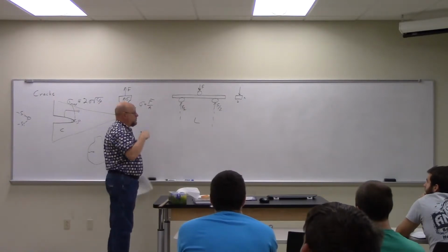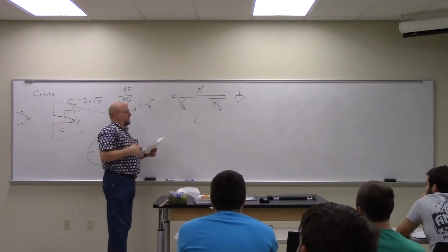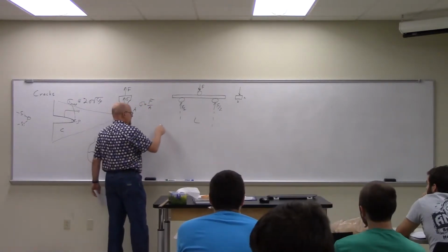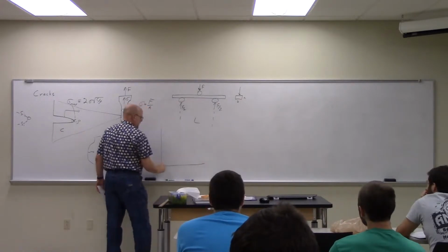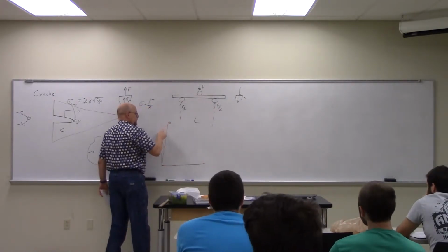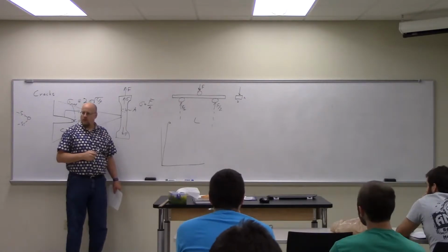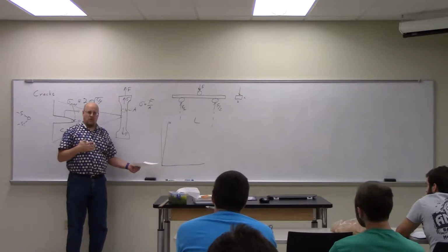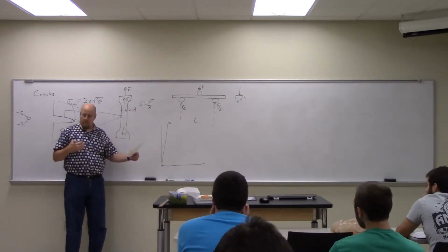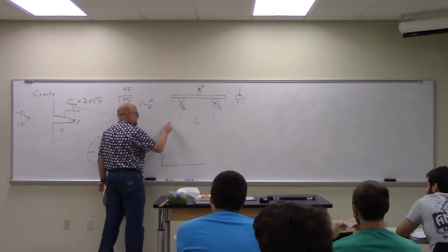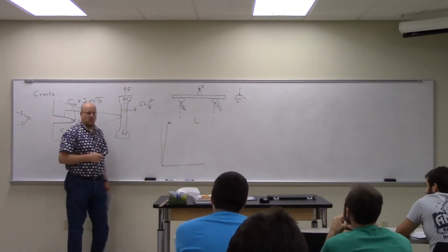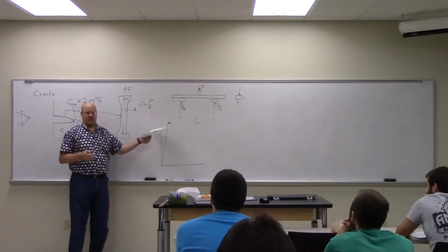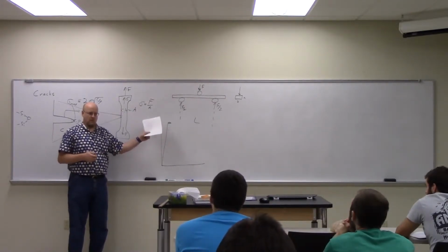So what you measure with a ceramic material, you want to know how strong a ceramic is. Now generally, as I mentioned when I did the tensile test, if you actually did a tensile test on a ceramic, it would do this and then it would just sort of break, because there's not a lot of plasticity in a ceramic material. It's brittle, it doesn't deform. So all we really care about is this one breaking stress. We typically don't care so much about yield stress or tensile stress. They're all kind of the same thing because it all happens at about the same point.